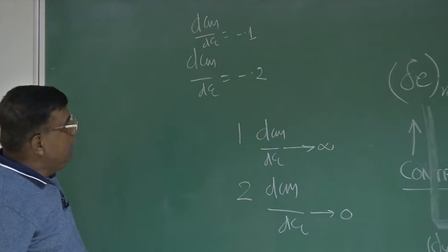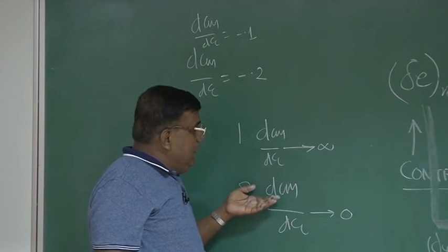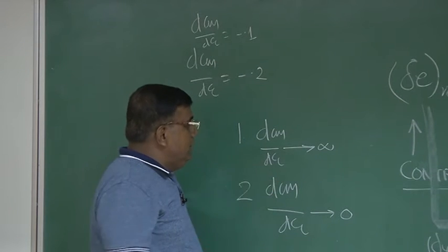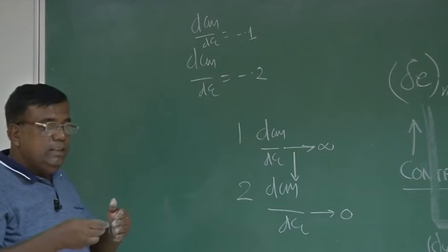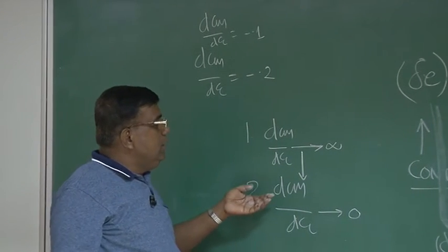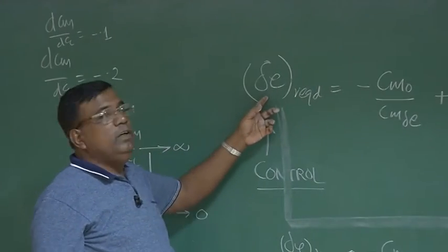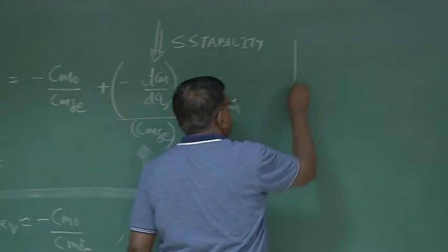Okay. So coming back here, what does it say? That if I go on reducing the static stability, that is, I go on taking the xcg of the aircraft closer to the neutral point, then the requirement for delta E also will reduce, which we have seen just a few minutes back.